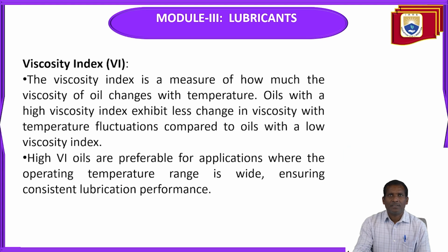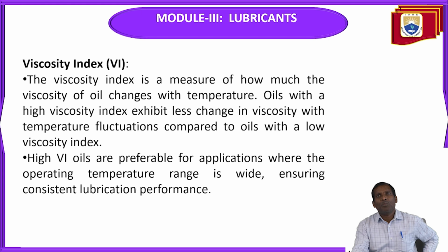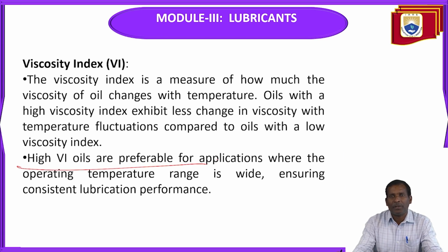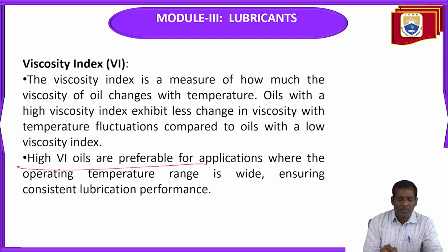Next, viscosity index. It is a measure of how much the viscosity of oil changes with temperature. Oils with a high viscosity index exhibit less change in viscosity with temperature fluctuations compared to oils with a low viscosity index. So high viscosity index oils are preferable for applications where the operating temperature range is wide, ensuring consistent lubrication performance.